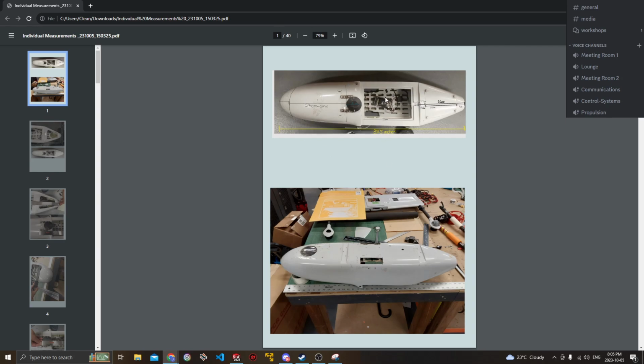We can actually create all those holes, all the things that we need to do, this hole here, and we can just thicken it, and it will remain the same dimensions, and we can make it ever so slightly bigger, but the dimensions of the thickness of this will match what is there in real life. And we can thicken it from the outside in. That way the dimensions we read in real life will be accurate on the outside, and then we extrude by the certain amount towards the inside that the drone actually is in real life, and that way we can pull dimensions from the inside as well.